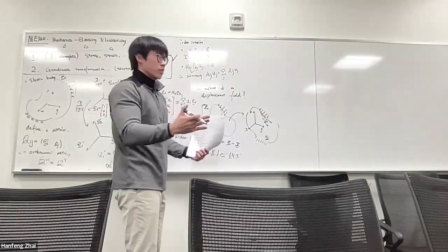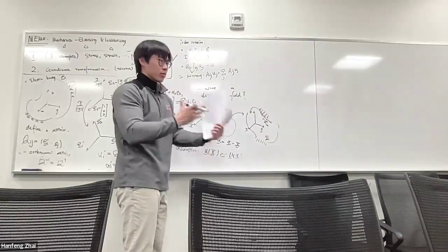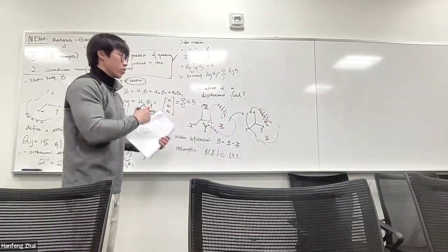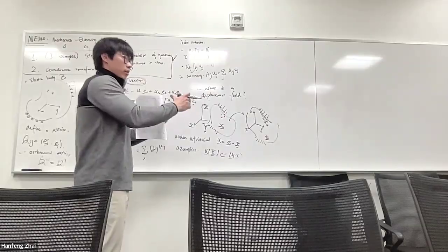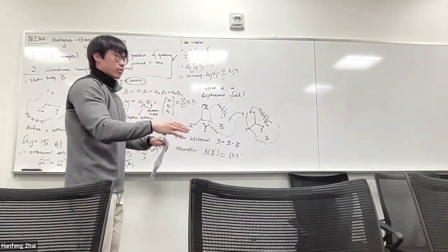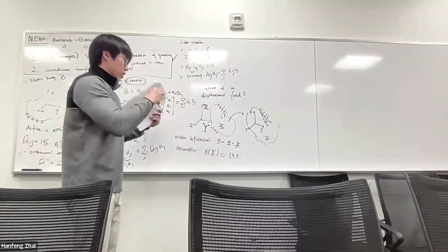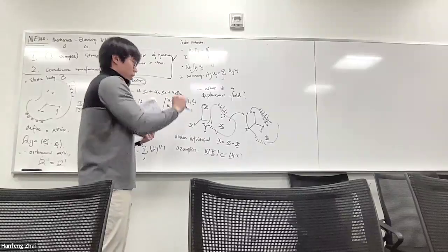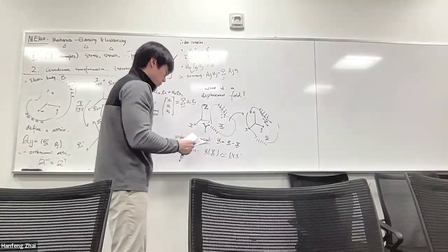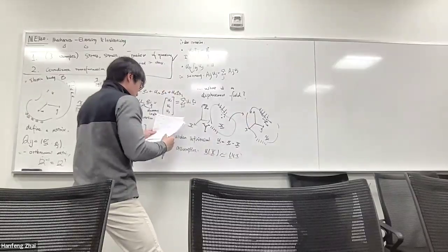If you're interested in learning how to represent large deformation, where you have to distinguish the difference between the two fields, you can take continuum mechanics, where you will learn how to use the deformation gradient tensor to represent the transformation of the field. Based on that, you can define new stress and strain under different configurations. But for the sake of this class, the analytical solutions that we'll be deriving are based on the assumption of infinitesimal small deformation, which means there are no differences between the two configurations, and the displacement fields are approximately the same under the two coordinates.